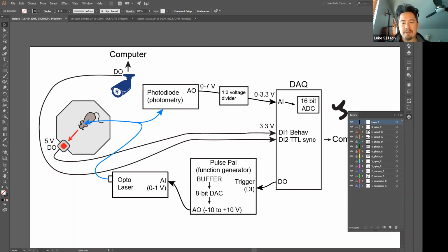So among stuff you're using, for example, lasers that have high-speed inputs can be sensitive, and they don't have any protection circuitry. If you use things like Arduinos, if you do the slightest thing outside their range, it burns out that pin permanently. Other things like National Instruments hardware, for example, is very expensive, but is very robust in that regard. Like you can plug in some 60-volt thing backwards, like I've done, and it's just fine afterwards. So anyway, it's just something you have to be aware of.